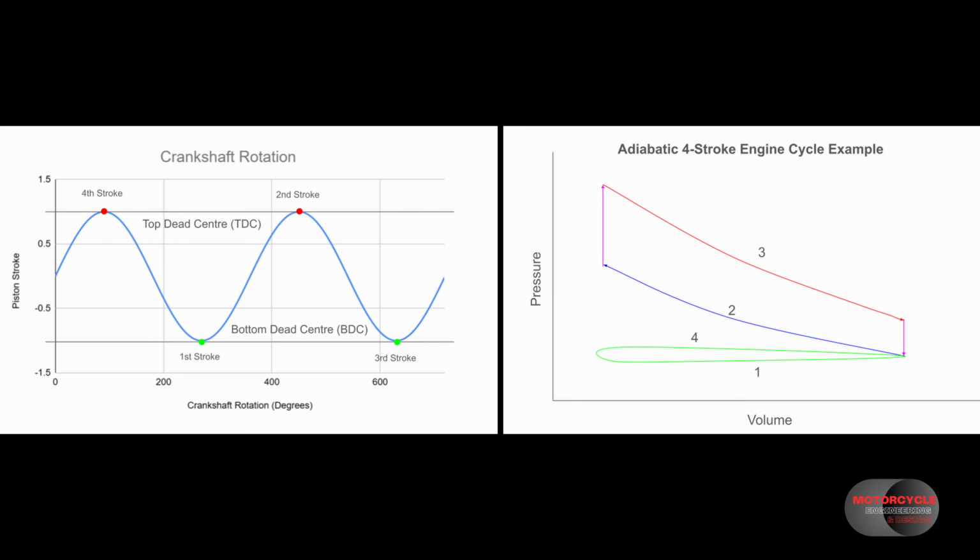The sudden jump in pressure on the far left is due to combustion, and the sudden drop in pressure on the far right is due to the release of pressure when the exhaust valve opens. So the intake valve is only open during the intake stroke, and the exhaust valve is only open during the exhaust stroke. Each valve then is only open for 15 to 20% of a cycle. The cams aren't acting directly on the valves, they are actually acting on the buckets or followers which hide the tappets, the valve retainer and the spring.